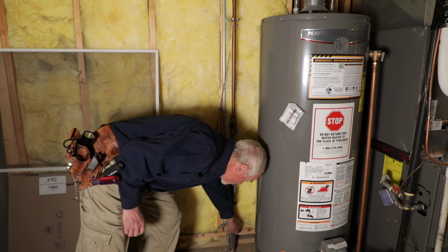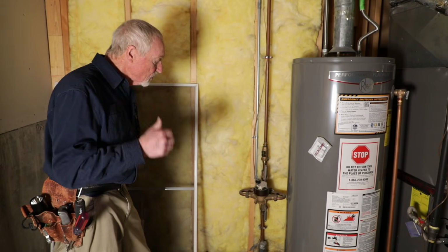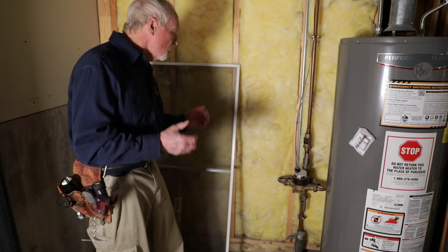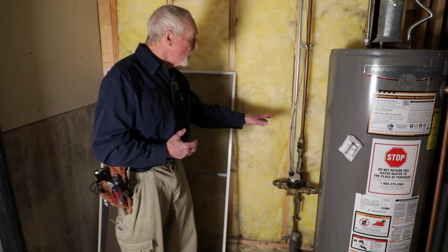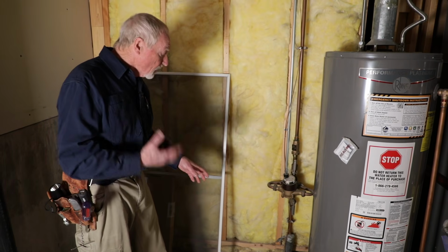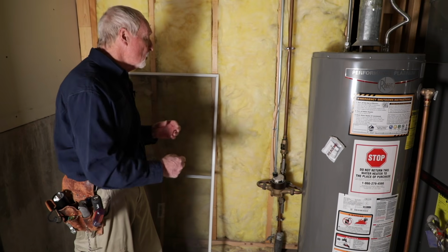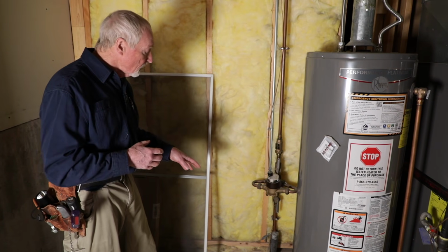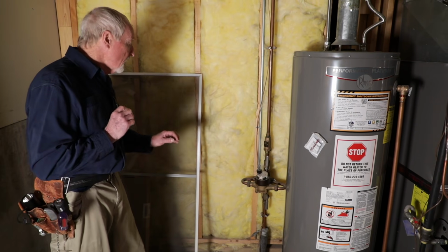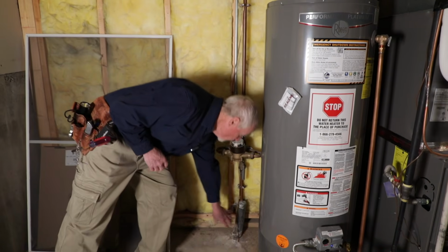Somebody put a sleeve around the copper pipe coming through the slab, which is exactly what we want to see. Whether it's simple plastic, paper, something that isolates that copper pipe from contact with the concrete, for two reasons. If the concrete slab moves and it's holding onto the pipe, it can move that pipe with it, maybe break something. And the other thing is mineral salts in the concrete can react with the copper and damage the copper, weaken it, and cause a leak. So we want to see this sleeve here around it.